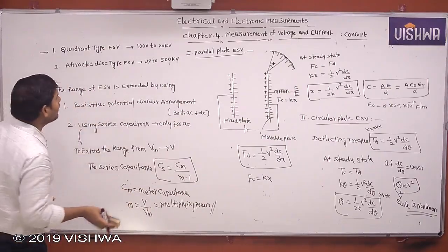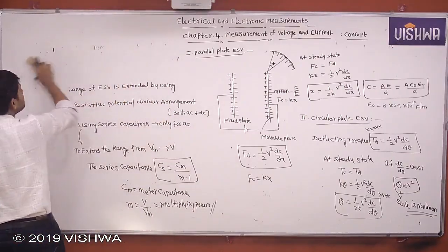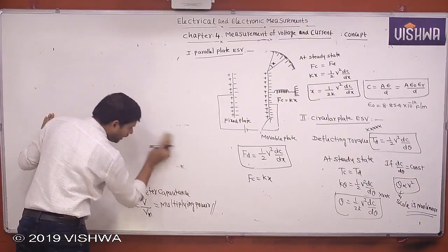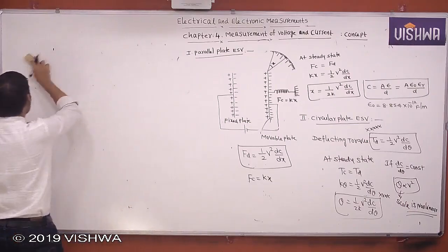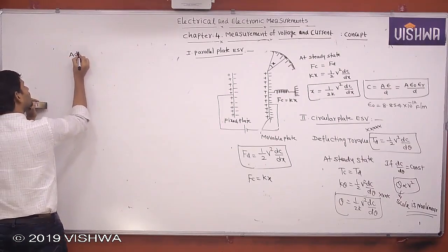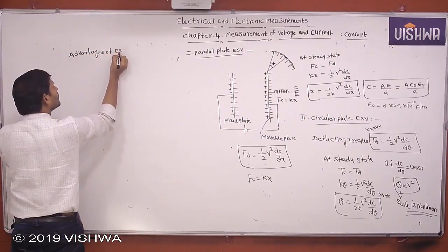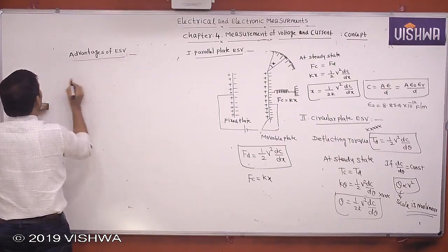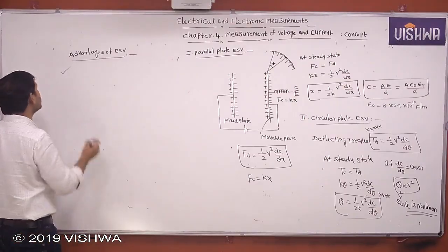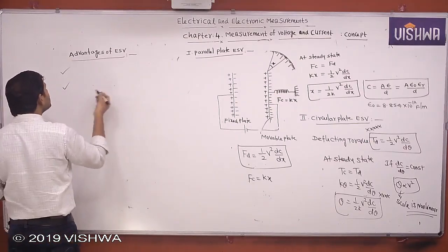Now tell me, what is the advantage of electrostatic voltmeters? Can you tell me what is the advantage of electrostatic voltmeter? I told already, to measure very high voltages for any type of waveform, we can use the electrostatic voltmeter. That is one advantage. The second advantage is, these instruments are free from